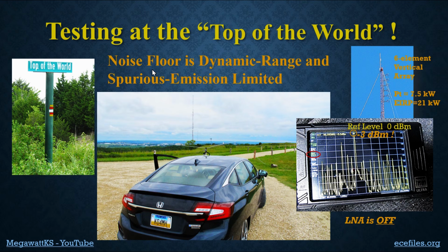So here, up at top of the world, the noise floor, the minus 100 that we're seeing here, is really dynamic range limited. And that's partly due to the fact that spectrum analyzers are designed to see all kinds of signals. They don't have pre-select filters for tuning and so forth. I also think that some limitations are due to spurious emissions.